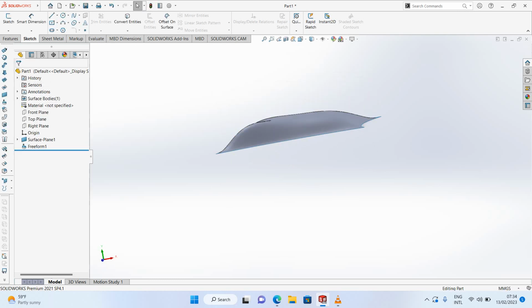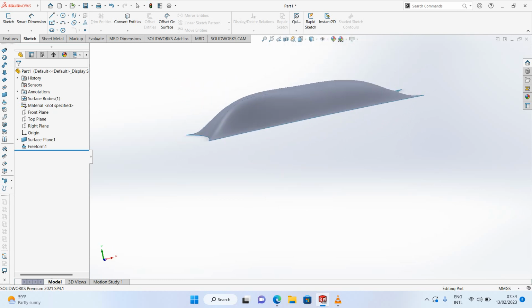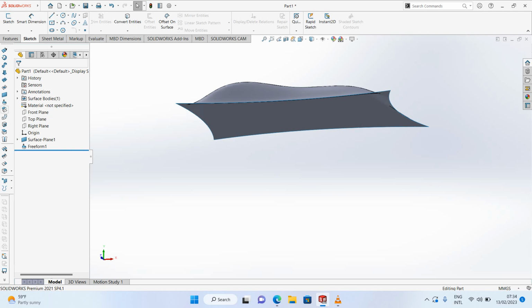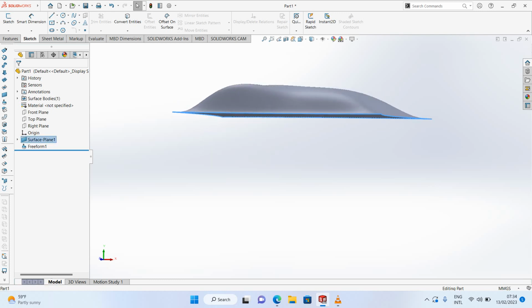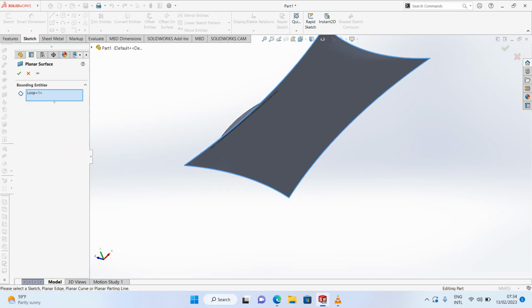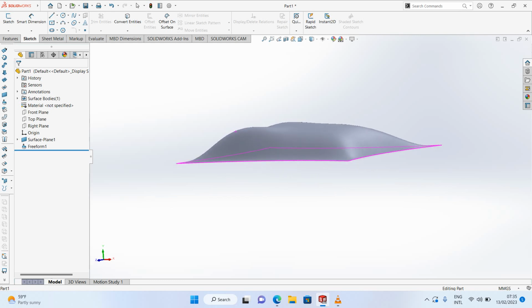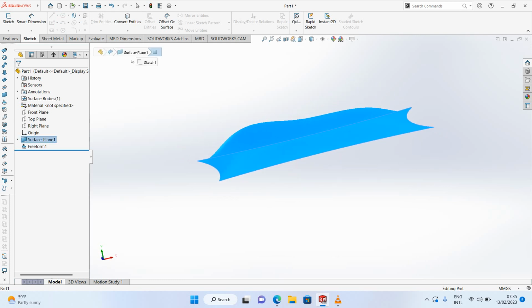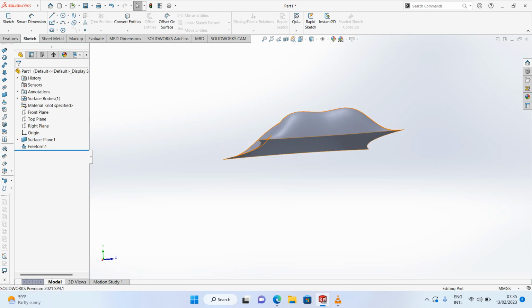So now we have this form. If we want to make this to be solid, you come on this side here, you use planar surface. So for this case, you have to select the whole loop, like so. Then say, add a planar surface, click OK. It's bringing an error. That means you need to check something if everything is okay. Now I have to select this surface and inspect it for any problem that might be existing.